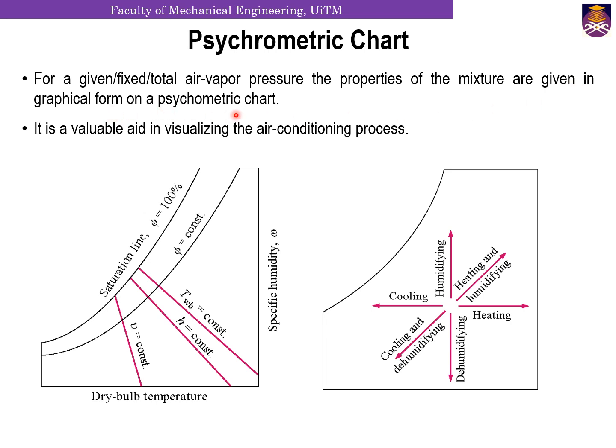You can see that the state of the atmospheric air at a specified pressure is completely specified by two independent intensive properties. So you can have any of these two properties. You can use that to specify the condition of the specified pressure or the air properties that you have. The rest of the properties can be calculated easily from the previous relations, right? You've done that in the previous sections.